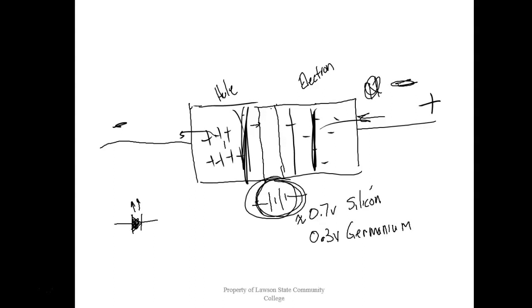As long as we don't exceed what they call a breakover voltage, we're okay. Sooner or later, if you have enough voltage, you can push current through anything. And if we push current through that depletion region when it's real big, it's dropping a lot of voltage and it literally burns the diode up.